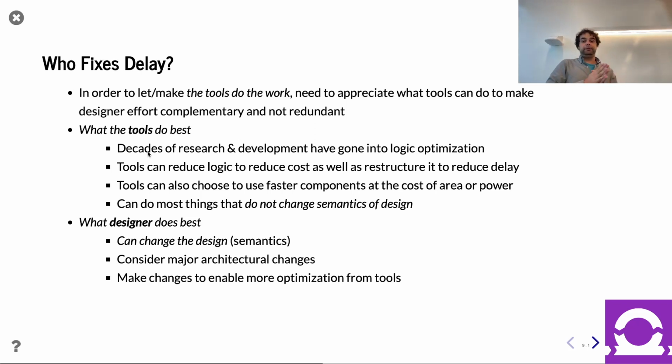It can also burn more power to try and really save the critical path. Okay, I'm going to use these bigger, faster gates, burn power in the critical path, hopefully saving the design in the long term. The point is, all these changes do not change the semantics of the design, right? They use logic transformations, but it's still logically equivalent, right? You should still pass the logical equivalence check, or LEC.